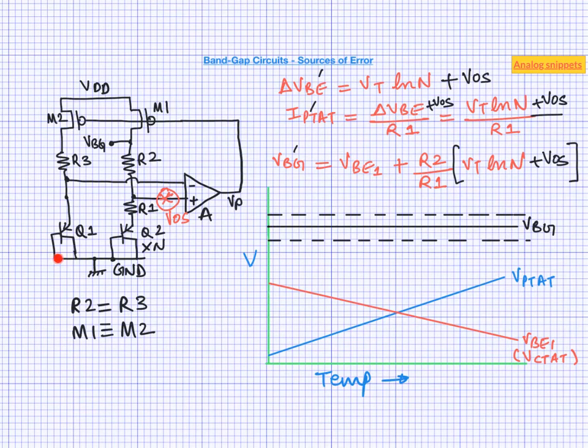So what are the limits on n? Apart from obviously area, because larger n will consume more area, it is defined by the limits of the current where the BJT model is very well defined. So if we increase the n for a given value of current, the current in an individual BJT finger reduces. On the other hand, if we maintain minimum current in the BJT, then the current in Q1 increases with increasing N.